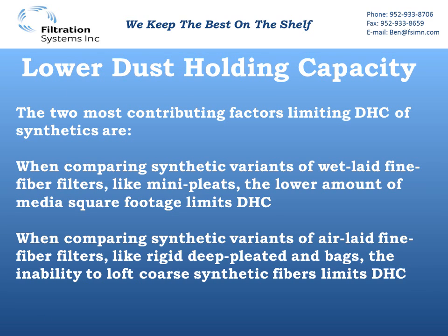So tying all of these points together winds up in a lower dust holding capacity. Lower dust holding capacity means shorter life, and you reach final static, you have higher static pressures sooner. So any initial energy savings is quickly used up and gone away once the filters begin to load. And when we compare synthetic variants of wet laid fine fiber medias, which would be predominantly your mini pleats, as we saw earlier, it's just a significantly lower amount of media per square foot, which limits the dust holding capacity. You just don't have as much there to catch dust.